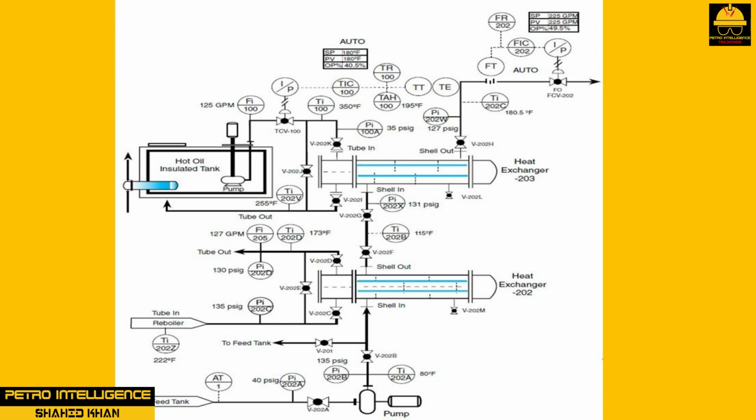The differential temperature, delta T, is 49 and the difference in the tube inlet pressure at 135 psig and the tube outlet pressure at 130 psig is delta P, 5. Process technicians carefully monitor these differences over extended run times. Heat exchanger 203 also has a tube inlet and a tube outlet as well as a shell inlet and outlet. Pressure and temperature are carefully monitored and tracked on checklists and statistical process control charts.